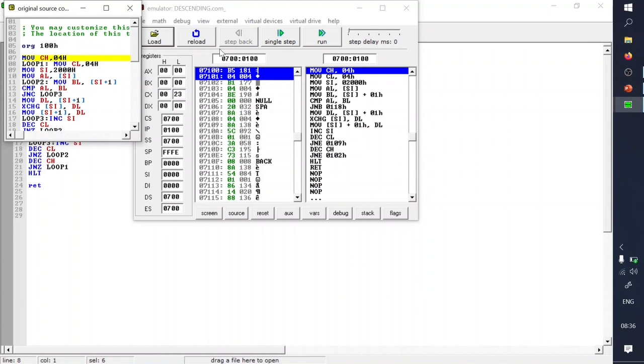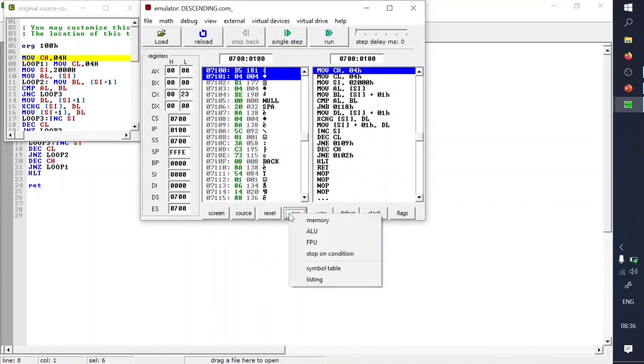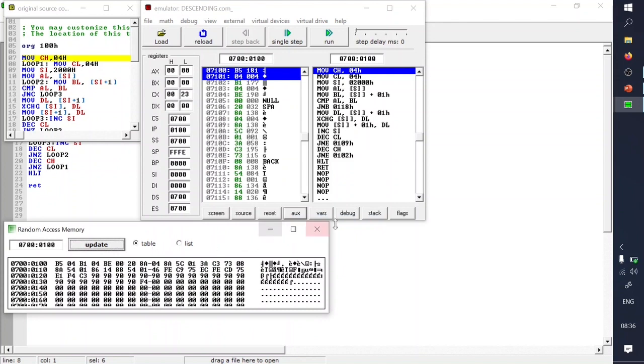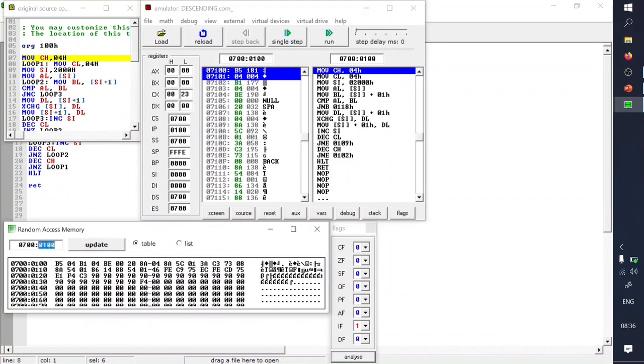Yeah. I can check with my memory locations, AUX memory. I can check the flag status also here, and I can put those elements here. Your data segment register is going to start at 0700. So it is at 0700. Your memory location is going to be 2000, so I'm going to give the value of 2000 and update. I have to make it in descending order, right?